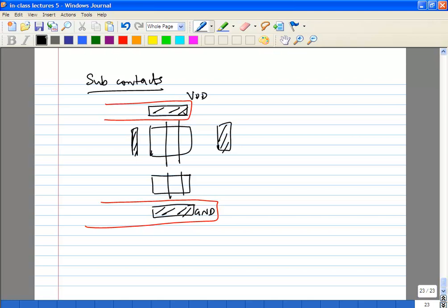So you want to prevent that, so you want to give a very good substrate contact, and typically there will be specialized RF transistors which are very well modeled. So if you look at the basic transistor model, they basically just model all the way up to M1, probably just enough to give contacts and connect it out. Any metal lines added up are not modeled. If you add substrate contacts, they are not modeled.